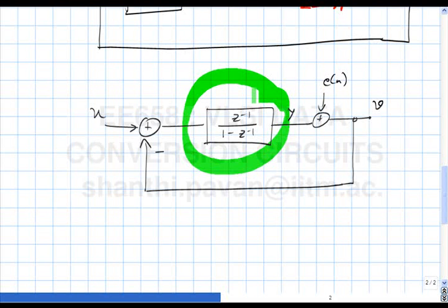So the switch capacitor integrator is one system which keeps accumulating the input, and so if you have higher order systems, higher order loop filters, all you will do is have many. If you have an nth order loop filter, then you will have n accumulators in the loop filter, and then you have some weighted summation of the outputs of each of these accumulators to give you whatever loop filter it is that you want.